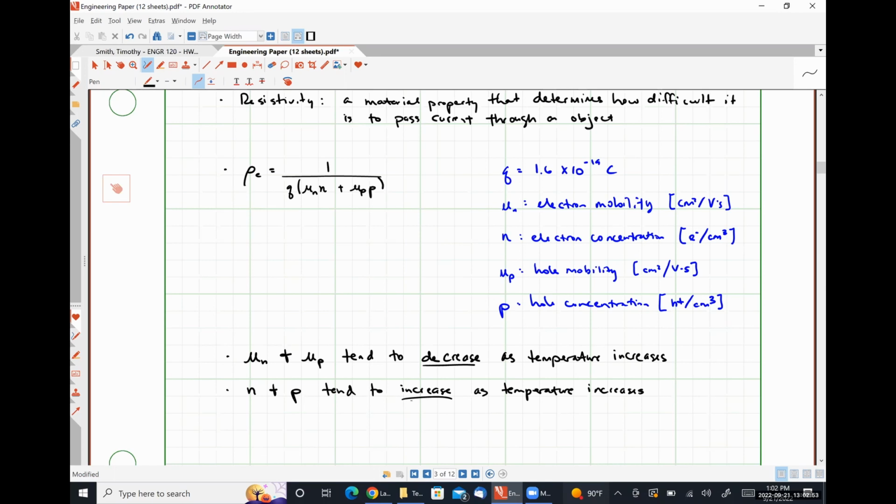When you had your thermistor, you used it in a simple voltage divider circuit, and I believe the thermistor was at the bottom part of your voltage divider. If you had a positive temperature coefficient thermistor, it would have needed to go as the top branch in your voltage divider circuit to effectively get the same trending, where you would see the voltage increase as the temperature increases using your little sensor, okay? So all of that to say, this is something that you've dealt with very slightly 4 years ago, so it's not entirely new.